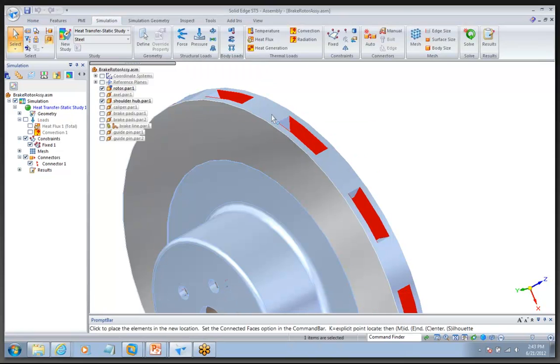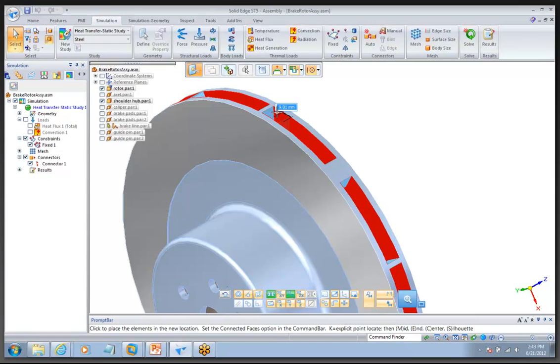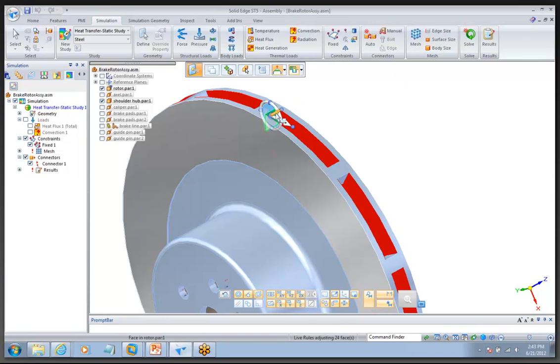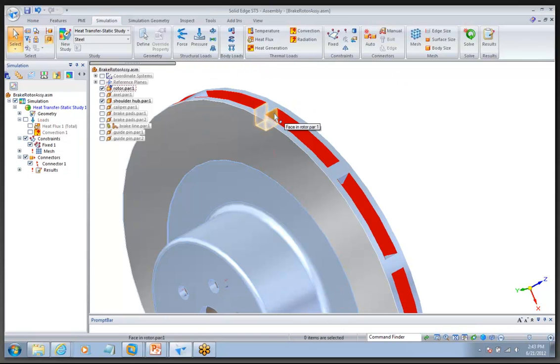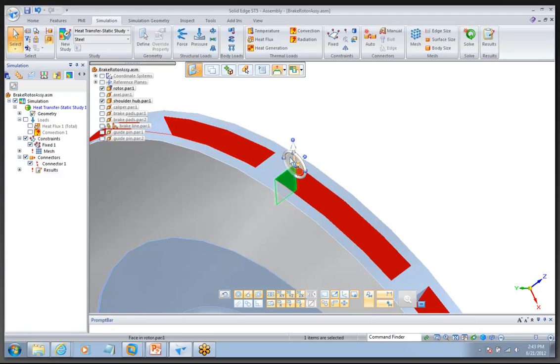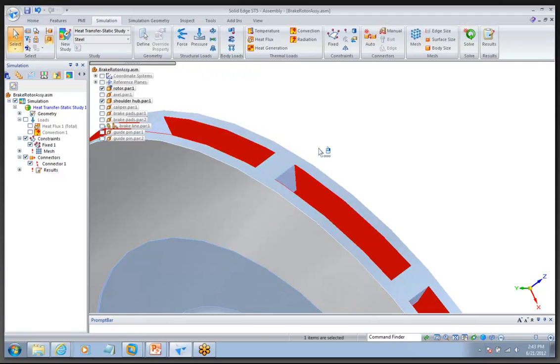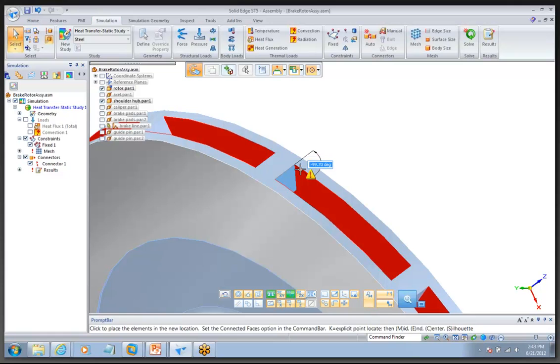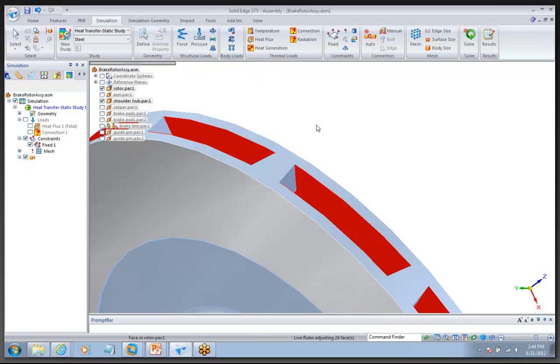I'm going to move this back using my synchronous tools, which are very handy, to, well, let's say 12 millimeters. And then I also want to angle it out a little bit as well. I want to do that about 12 degrees as well. And that looks good.